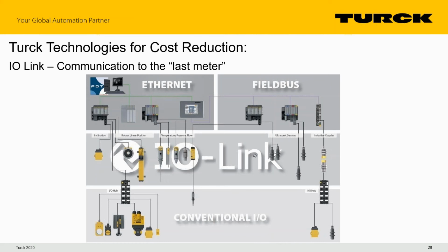If I'm using IO-Link, now I'm getting the process data serially, and there's no noise injected, and some of these devices have 27 bits of resolution that I get all 27 bits across the communications. So there's no loss of integrity in that data.